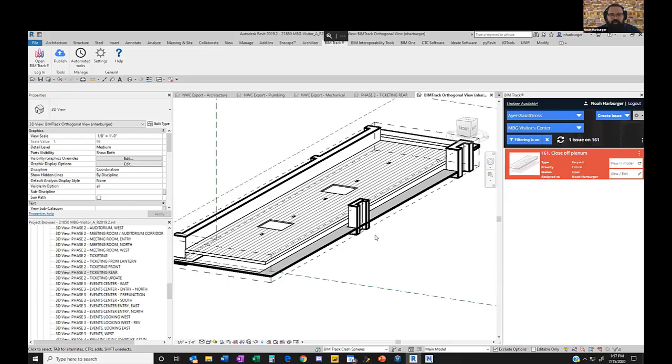I think during that initial review step, I'm literally just hitting the down button in Navisworks and asking, is this a problem or not? Is this a problem or not? Yeah. And mass ignoring tons of things. They're like, this just isn't a problem. We're not even looking at things generally that are less than 2 inches in diameter, because it can go somewhere. Like we can make it work. So we're trying to just look at the things that are going to potentially be harder. And if the team agrees, like, yeah, I modeled it here,